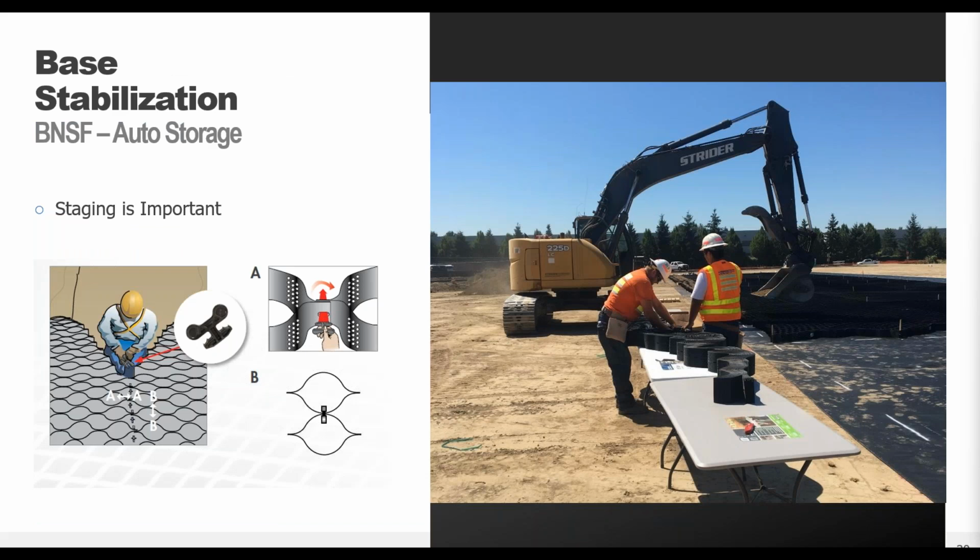Here's a best practice pro tip: staging tables, as staging is important for any large project. Here we see the use of staging tables where adjacent panels are connected prior to being expanded and then placed across the prepared subgrade.